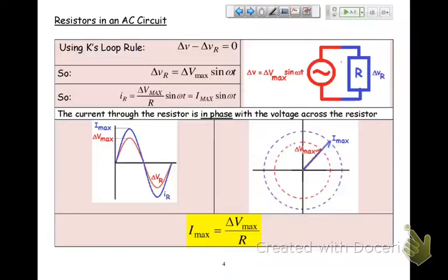And then we started talking about resistors, capacitors, and inductors in an oscillating signal circuit, an AC circuit. There were several points I wanted to get to. One was that we're used to the idea that when we have the maximum potential difference across a device, we get the maximum current flowing through it, because we're used to resistors. But ironically, because the capacitor and the inductor don't work the same way, that intuition doesn't necessarily hold.